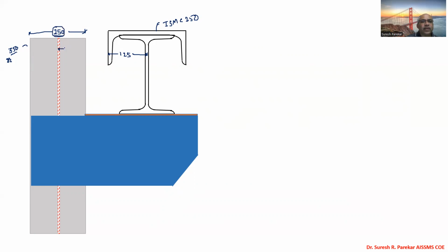So let us take 250, so we have this as 125. This 125, this 125. I kept this 50 as a cover. This may be reduced if my column size increases. If the column size increases, then automatically my width of flange increases and this cover may be reduced. Now we have this as ISHB column; you have to always keep in mind that we have to provide ISHB. As we have seen, for the gantry girder we are providing ISWB because the width of flange is greater.